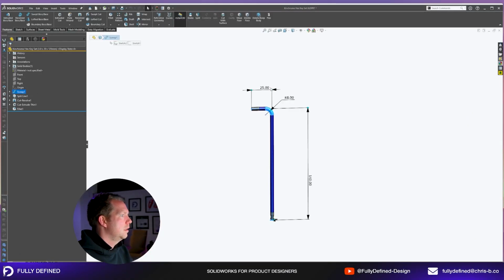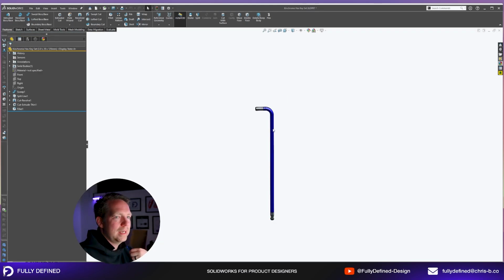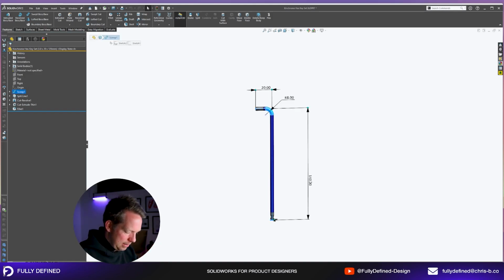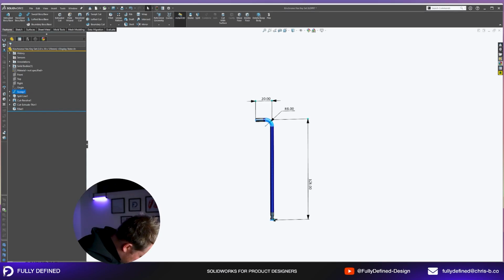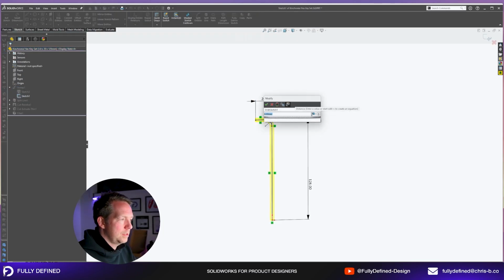Now, for this one, now that we've linked the sketches to this configuration, I think we're able to just click on the number and change it. Let's test it. So if I change 25 to 20, and then I go back, that works. Okay, so once you have done the linking to the configurations, it becomes even easier to edit, even quicker. Okay. Now we had not changed the radius, but we will change it this time. So we do have to edit that one and link it to this configuration that becomes 6.5.